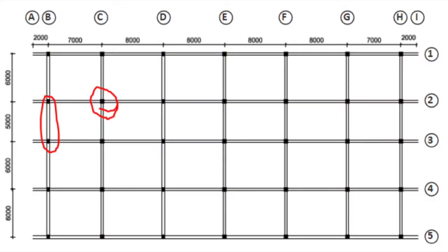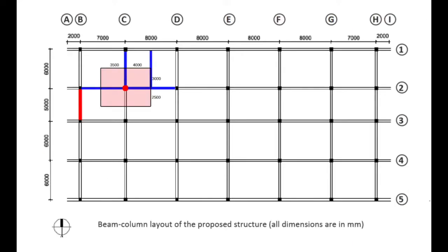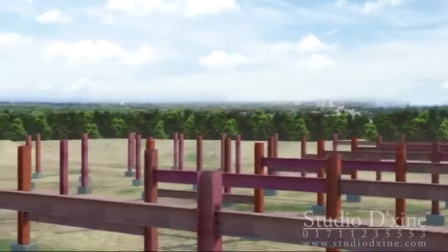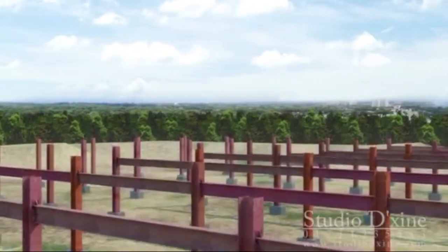The physical significance of these locations meant differing load options had to be calculated over their respective tributary areas, and as the beam is on the outermost point of the structure, it is required to hold much greater loads than the central beam.